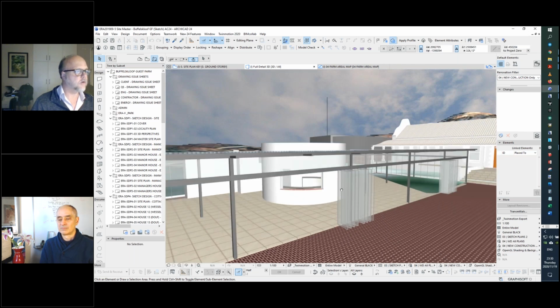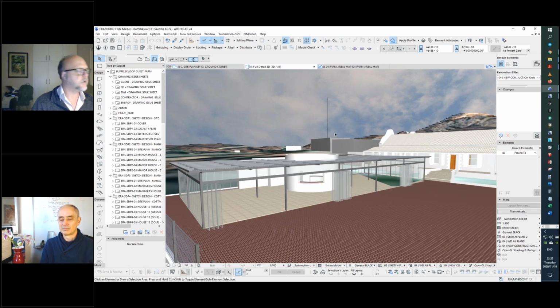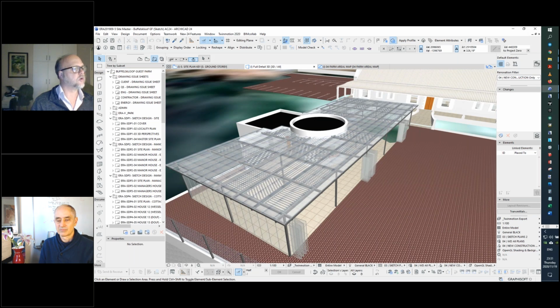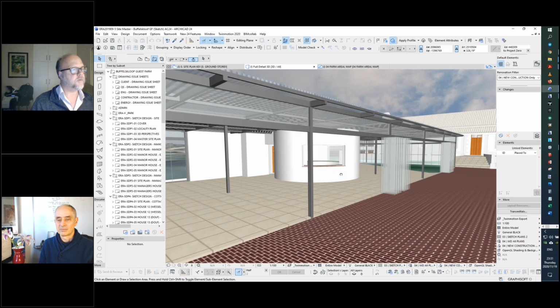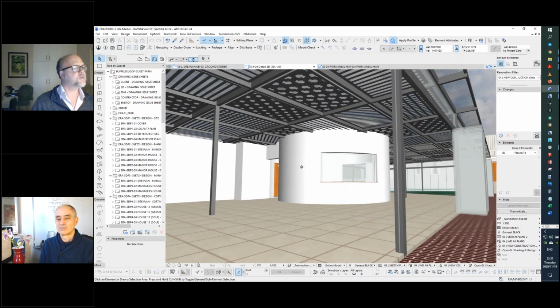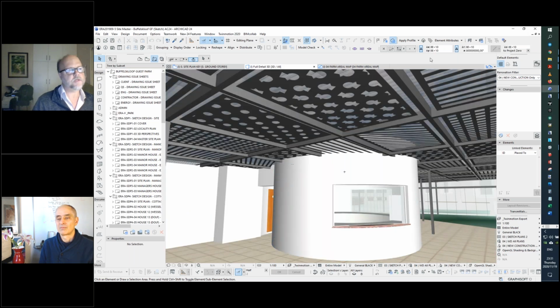And we created this as a totally opposite to the old heritage building, being very modern, literally a glass box. The design thinking here is the Karoo is a semi-desert area, so it's very hot. Despite that, we created this glass box of which the roof itself is also fully transparent. In order to alleviate the buildup of heat in this enclosed space, we've opened it up with frameless doors. You'll see the paneling in the roof structure in between the beams, just suspended panels with insulation material, and then chroma deck as a panel. And then we've cut different patterns into it, making an array of patterns.